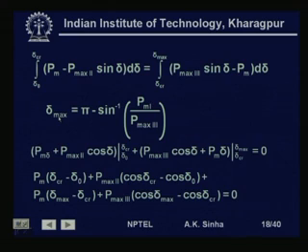So, putting for this, we integrate this, we get Pm, which is a function of delta, Pm into delta. I am sorry, this delta should not be in subscript mode, this is Pm into delta, because we are integrating this, plus P max 2 cos delta, since sin delta when we integrate becomes minus cos delta, and this is minus. So, plus P max 2 cos delta from delta 0 to delta critical.